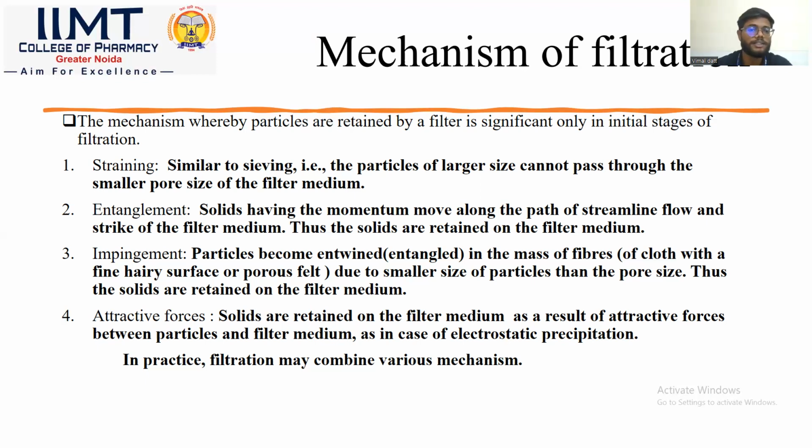So these are the basic mechanisms involved in the filtration process. First of all, it's straining. Straining is a common process in which we just sieve our product with the help of a mesh or any filter medium, in which the particles of larger size are retained over the filter medium. Second one is entanglement. Entanglement is basically a process of sticking between the pores of the filter medium.